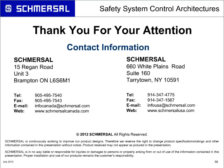And let me mention again that the schematics aren't complete because you'll have additional things such as fusing and thermal overloads for motor starters. But the presentation is just showing the concepts and what you're looking for on the safety side of things. But what is happening is it's referring to not auxiliary relays, because your safety monitoring relay is your auxiliary relay. It could be your motor starter.